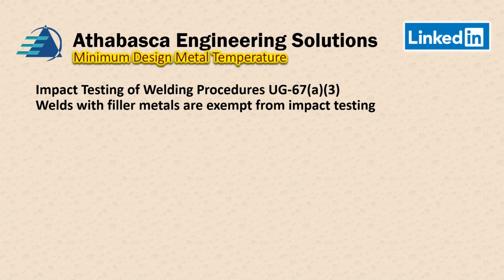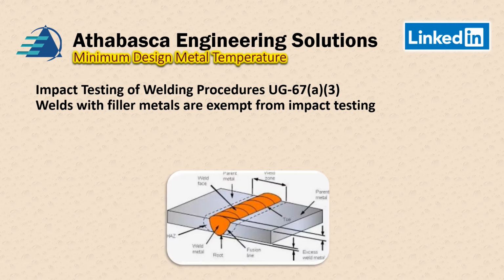Impact testing of weld procedures will continue with 67A3. This is welds with filler metals that are exempt from impact testing. A PQR with impact testing, that is the weld procedure with impact testing, is not required if the following.